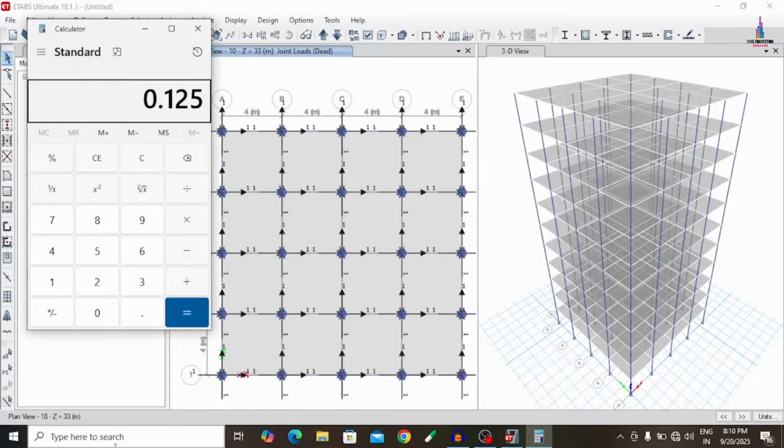For the internal wall, again in the same process we have to consider 3, again we have to consider 20. So this is the internal wall. Again for the parapet wall load, 0.125 multiplied by 1.2 multiplied by 20, so that it will make it 3. So 3 plus 7.5 plus 13.8, so that it will make the value 24.3 kilonewton per meter.